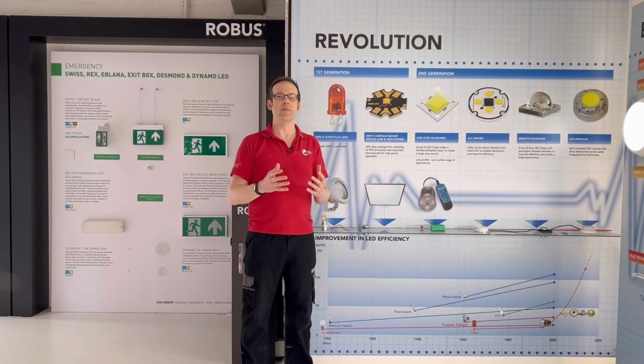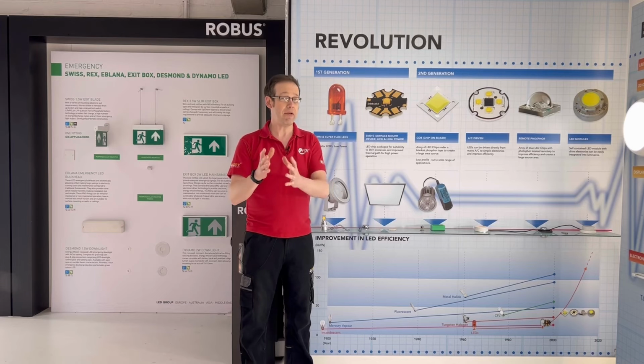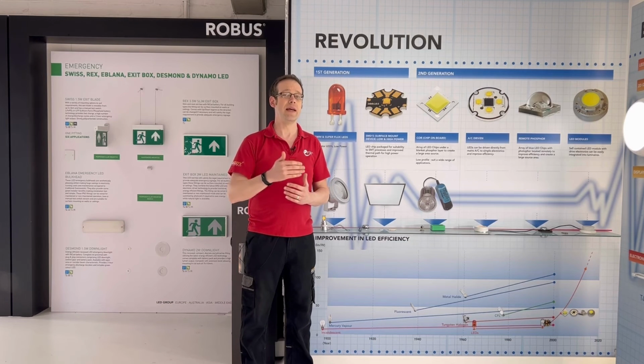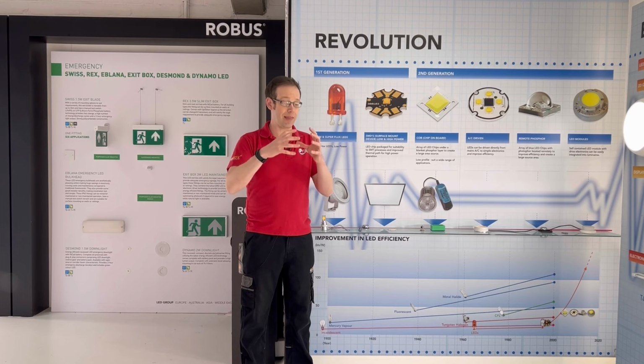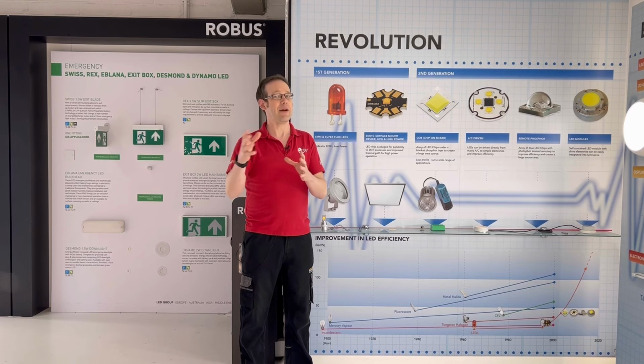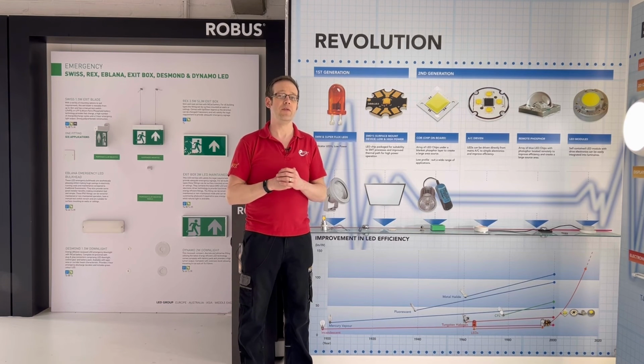So in lighting terms, there is such a thing as luminaire efficiency, which is a measurement of how much light a lamp outputs compared to how much light comes from a luminaire with that lamp inside it. This is because not all of the light makes it out of the fitting. Some of the light is absorbed by the inner surfaces of the fitting or just bounces around inside it. And some, of course, is absorbed by the diffuser as it passes through it to the outside world.